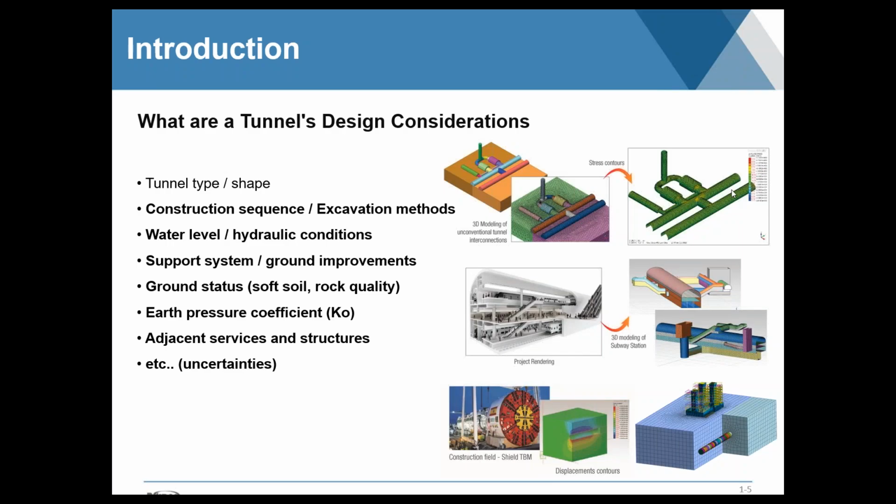And getting right into it on today's focus, which is, of course, tunnels, particularly tunnels in 3D. We're covering some of the main considerations that go into the design of these kinds of projects. So, of course, starting off would be the type of tunnel, which basically means the shape is going to be determined, as well as the reinforcement. And that, as we will see later on, can actually be done by different methods. Some can even do this by hand calculations, and it's usually done by a structural engineer.